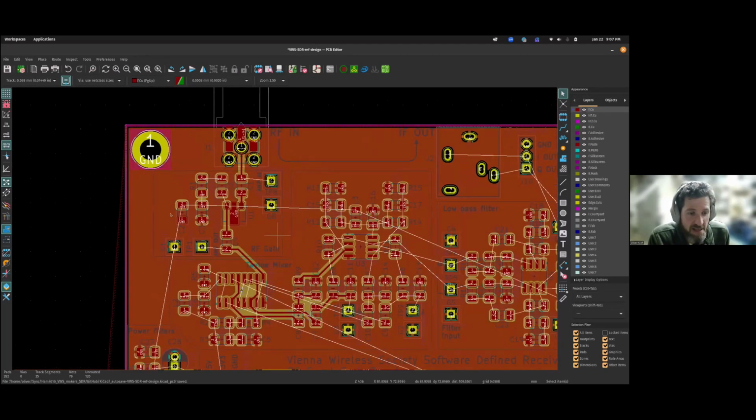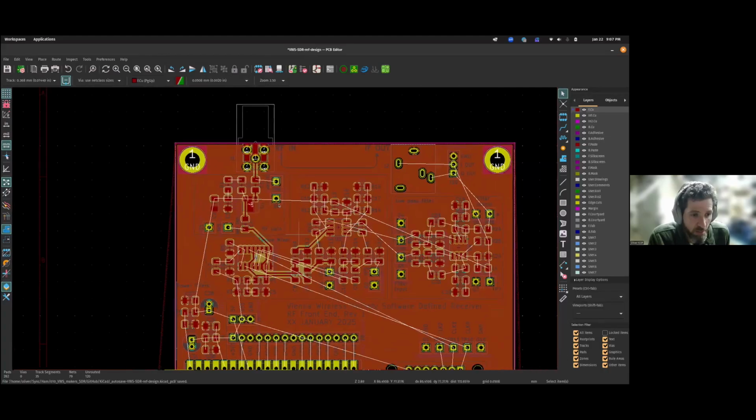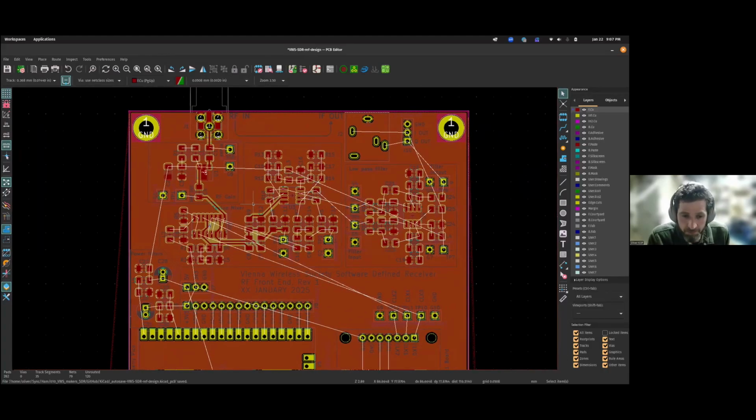So that's how to quickly fill out the copper ground plane. When you do this, there's a variety of videos I'll send around by email afterwards that really explain the benefits of putting vias in to tie your ground, to tightly couple your ground planes together.